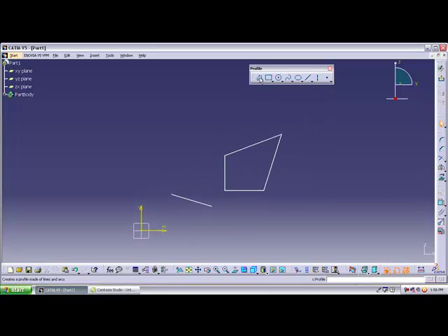Suppose you're drawing any line or any profile of an object, it should compulsorily be fixed. The straight line I drew should be straight only. But the line is not straight because it's moving, making 190 degrees, 70 degrees, 50 degrees. It should not be like this. If the line is drawn at 0 degrees, it should be fixed at 0 degrees. And if we align it to 90 degrees, it should be 90 degrees. So what is meant by constraining? Constraining means locking the diagram into perfect shapes.